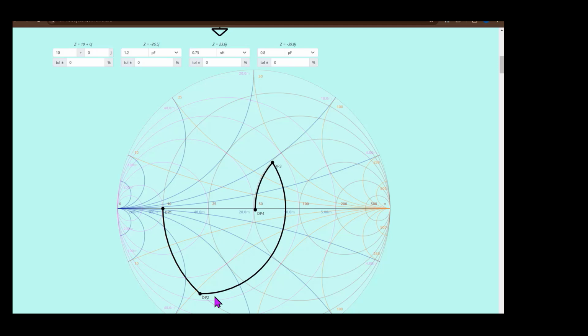When you say component Q, you mean like the Q of the inductor and whatever in series? Right. So an ideal inductor has a component quality factor of infinity. There's no loss in it. It's more or less the ratio of the energy stored to the power lost, so there's no power loss, so there's no resistance. So ideal components have infinite quality factors, but the network itself has a quality factor that's, to a first order, independent of the component quality factor, as long as the component quality factor is high.